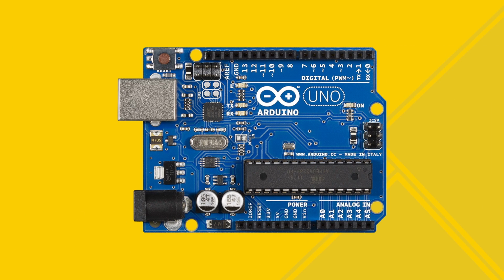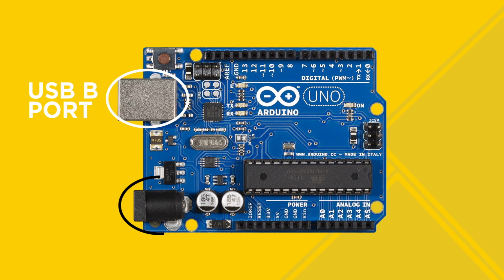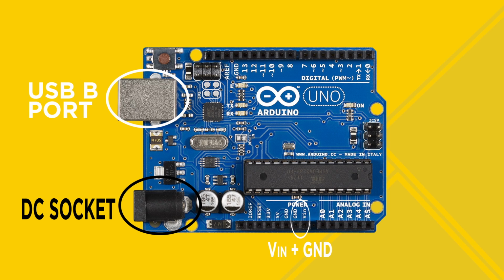Looking at the Arduino Uno board, there are three ways of powering it. You can either power the board through the USB port. If you have an external power supply, you can plug it into the DC power supply socket, or you can power the board via the V-in and ground pins.